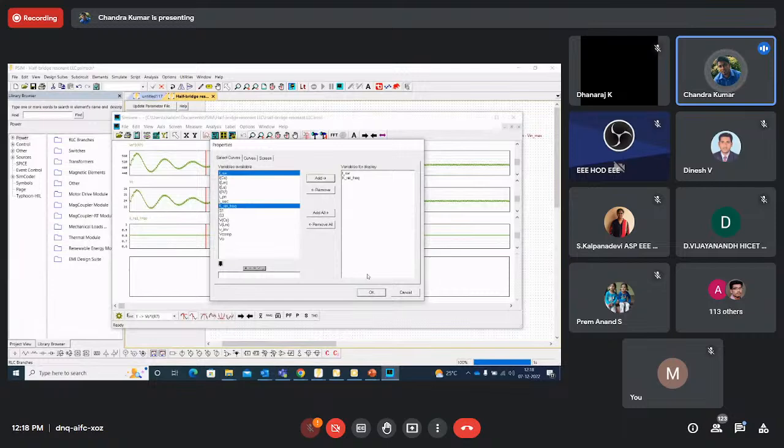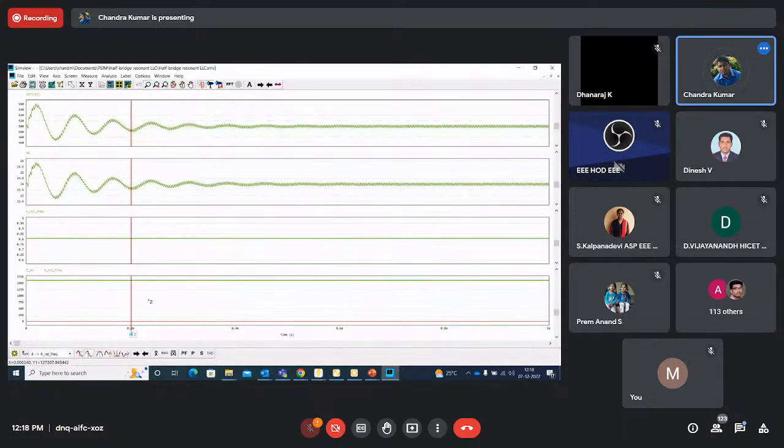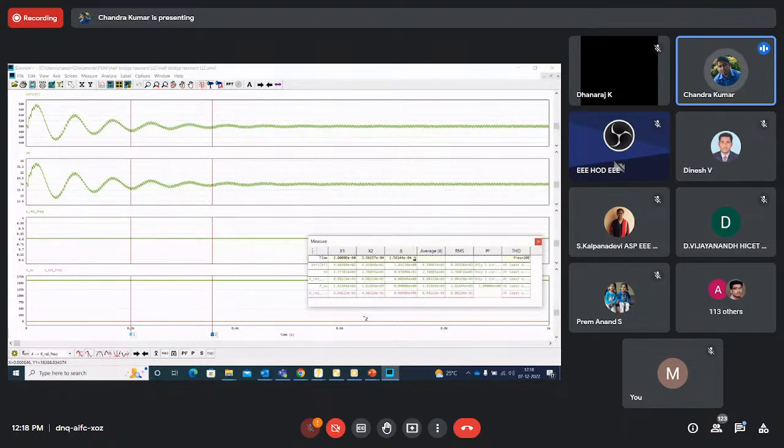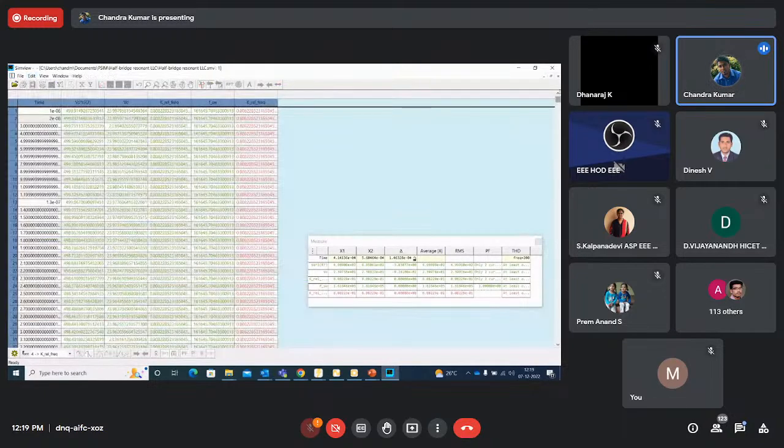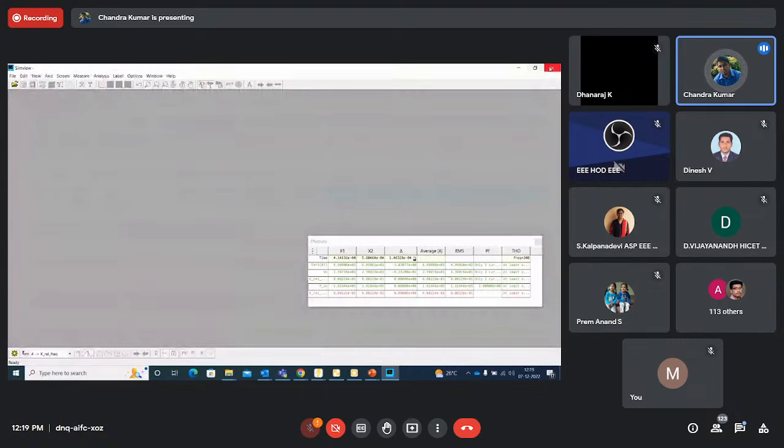What is your resonant frequency? You can just compare. You can just see here. And if you vary your parameters and want to compare the results, you can just keep it here and look at the difference here. So you can fine tune your parameters based on that. Okay, you can look at the output voltage is 24 volts, and you can look at the switching frequencies around 160. You can just look here. The ranges you can compare between this point to this point. What is the frequency? And then you can view your data points. Okay, so this is about the power supply.